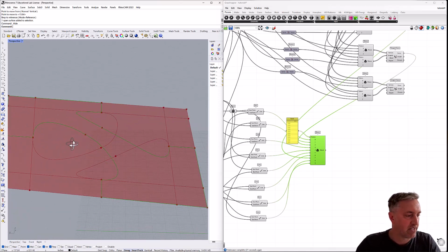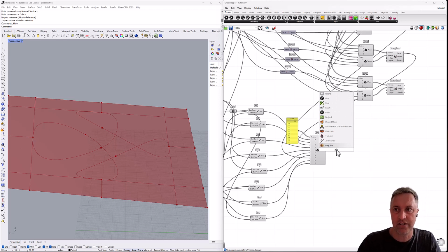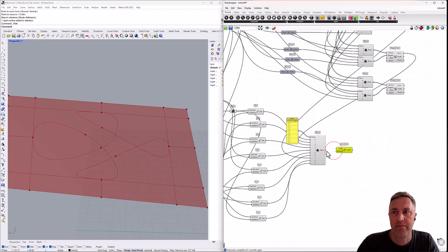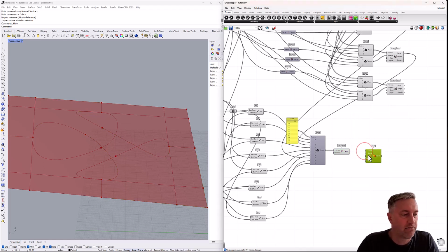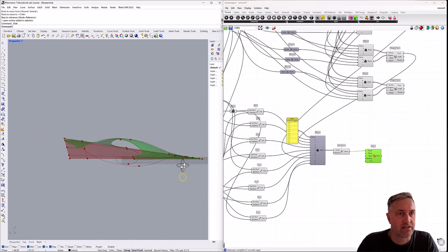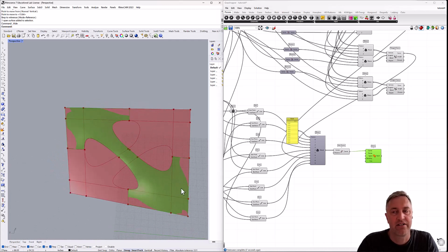So now our next thing is we can, I don't know if it's necessary to join them, but we can join the curves that come out of the weave. So we can hide that weave, we have the join, and now let's create a patch surface. So for the patch, what we're going to do is to bring the curves into the curves. And we can see the start of half of our panel here.